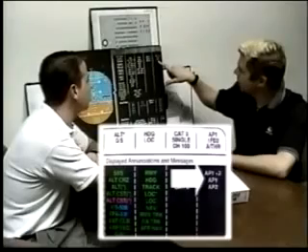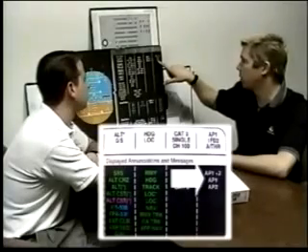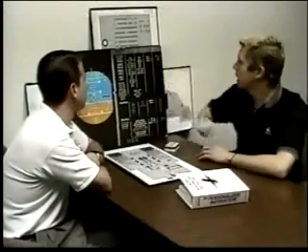Fifth column, AP1 and 2. AP1 and AP2 indicates that either Autopilot 1 or Autopilot 2 is engaged. AP1 plus 2 indicates that both autopilots are engaged, and that can only occur during an ILS approach after the approach button has been armed.